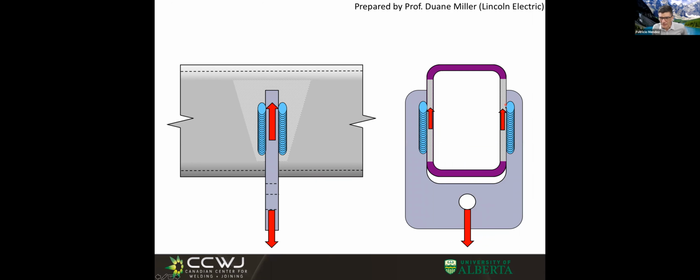Here we have the Abraham Lincoln Beard solution, right? How about this one? And here's showing again a gap so you don't weld it. Can you weld it? Yeah, you can. Do you gain anything? No. You lose anything? Yes. You lose lots. You lose time. You lose money. You put weight. You have a chance of a defect.